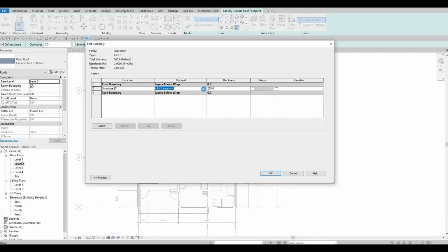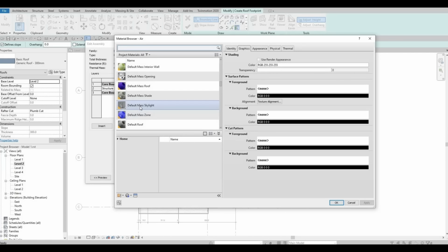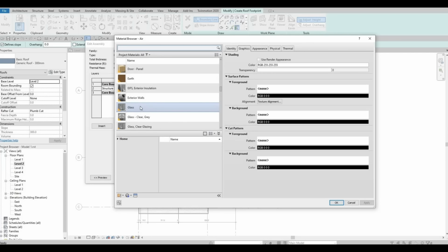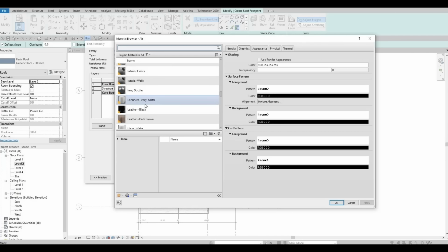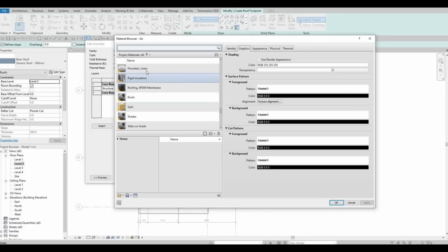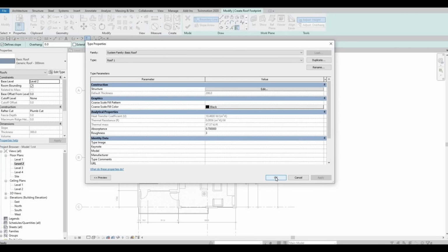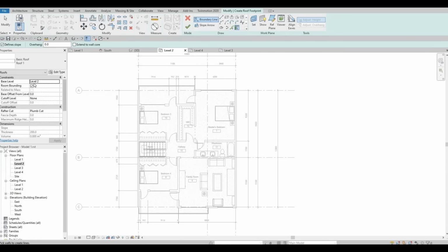We just need to set anything that is different from the others, so that once we move it to Twinmotion, we can set it up there as its final material. Here I'm just checking which one I haven't used yet, so I haven't used this one, and then OK, and then OK. Let's change the base level to level 3.